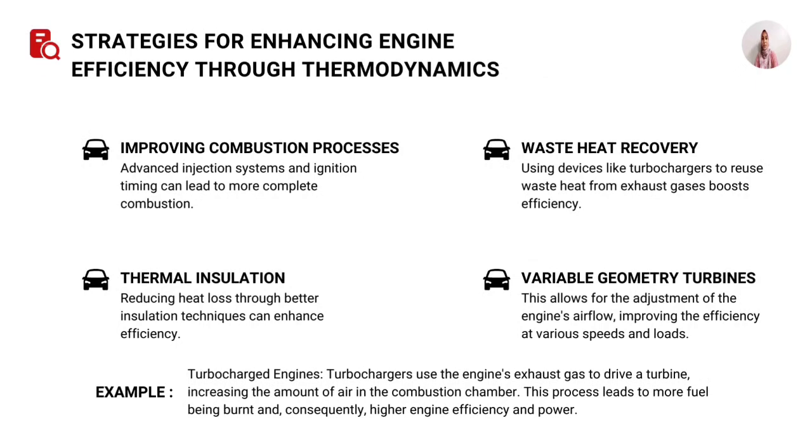So for the last one, I'm going to talk about strategies for enhancing engine efficiency through thermodynamics. First is improving combustion processes, which is that advanced injection systems and ignition timing can lead to more complete combustion. Next is waste heat recovery, which is using devices like turbochargers to reuse waste heat from exhaust gas to boost efficiency. And the next one is thermal insulation, which is that reducing heat loss through better insulation techniques can enhance efficiency.